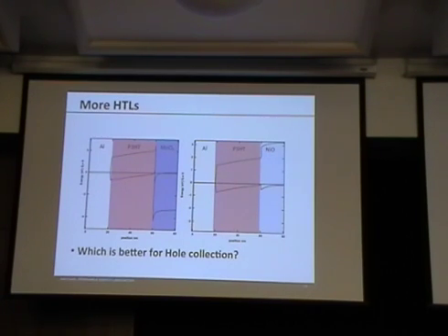That doesn't mean that the recombination in your device is actually happening at the junction between these two. It's happening in the interface as we've defined it, which means that it could be happening essentially in what some people might consider the bulk of the active layer, or throughout the active layer.